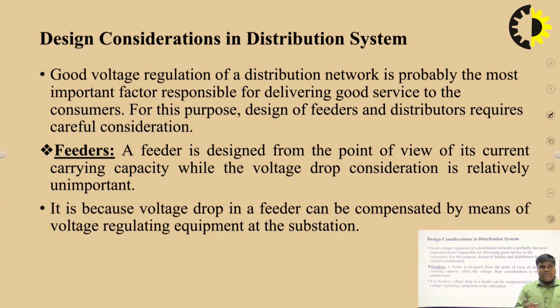substation. Okay, if we talk about the distributors, a distributor is designed from the point of view of the voltage drop in it, because the voltage consideration is the utmost important thing when we discuss the distributors. It is because a distributor supplies power to the consumers, and there is a statutory limit of the voltage variation at a consumer's terminals, which is to be plus minus 6% of rated value.